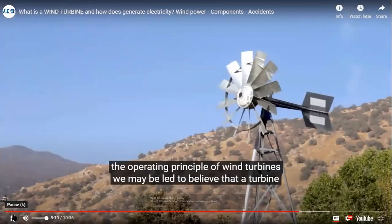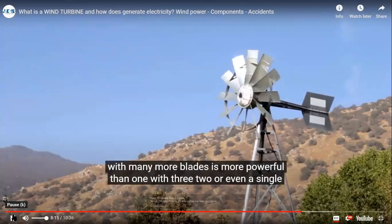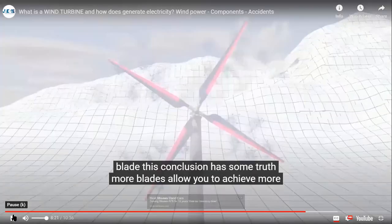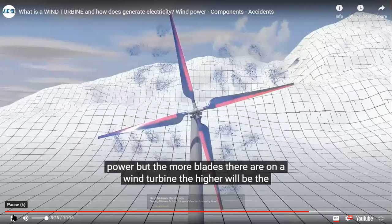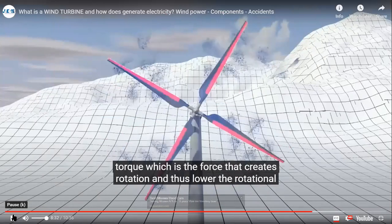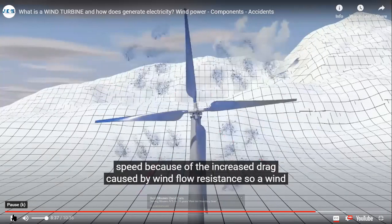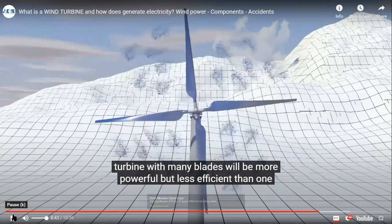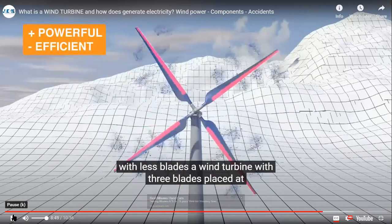By observing the operating principle of wind turbines, we may be led to believe that a turbine with many more blades is more powerful than one with 3, 2, or even a single blade. This conclusion has some truth. More blades allow you to achieve more power, but the more blades there are on a wind turbine, the higher will be the torque, which is the force that creates rotation. And the slower the rotational speed, because of the increased drag caused by wind flow resistance. So, a wind turbine with many blades will be more powerful but less efficient than one with less blades.